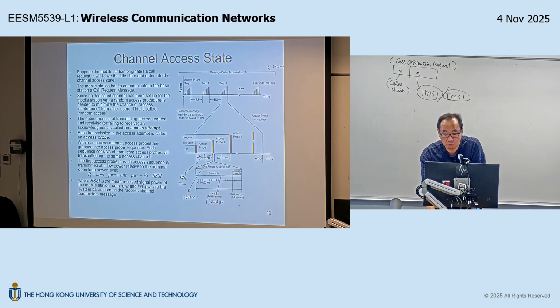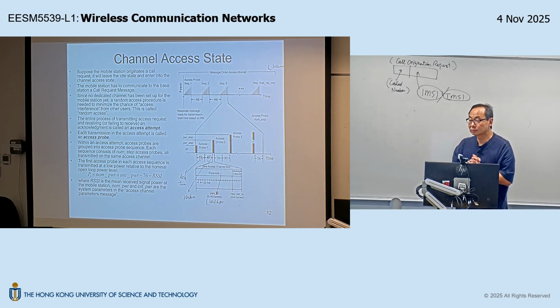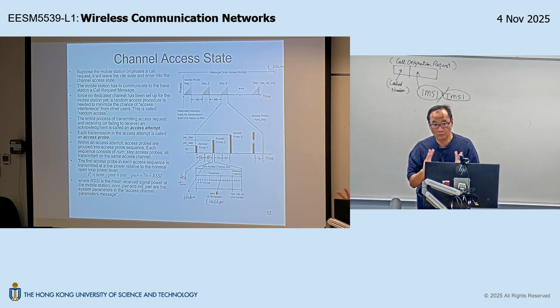So you start with a humble voice first, instead of shouting at the beginning, hoping that everybody will just transmit with just the sufficient power, without excessive power. Because this excessive transmission is not free. This excessive transmission will raise your interference level and reduce the capacity. Is that okay? So for every random CDMA system, you always have this behavior.